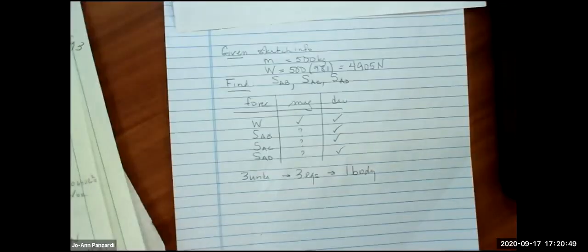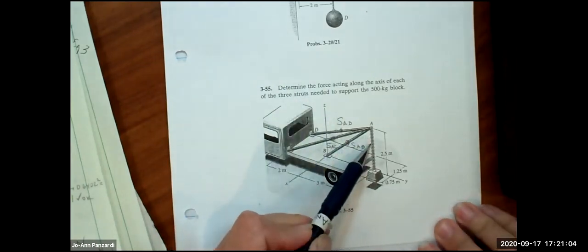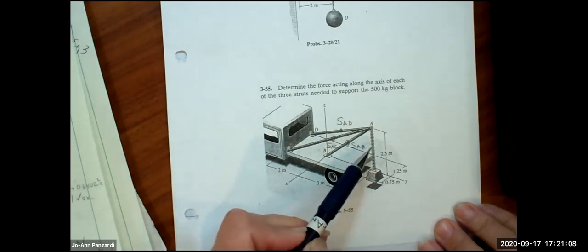And it's going to be 3 equations and 1 body. And why only one body? Because it's a 3D problem. Right, it's a 3D problem and we can get 3 equations: the sum of the forces in the x, the sum of the forces in the y, and the sum of the forces in the z, equal to 0. Okay, so now let's take a look at this. What's the force in the chain? Wait, Jason with an E.